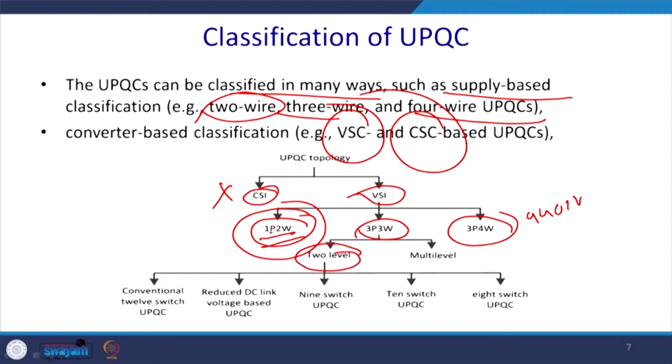Here this 2 level is used for single phase as well as mostly for the 3-phase 4-wire system. But in case of the 3-phase 3-wire system, since the voltage can vary over different voltage levels, we may require to use the multi-level inverter, because with IGBTs, we know that the cost of the IGBT goes high at the rate of the square of the voltage rating.